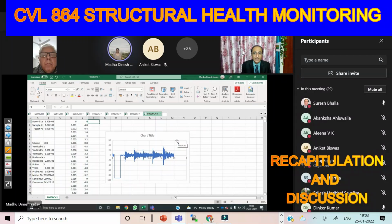So how do we define the 9th peak? This first file has peaks from 1 to 5, so the next file will have the 9th peak. That's how you randomly choose the peak and find out what the voltage is at that particular peak. Then you convert that voltage into strain. That's how you get the dynamic strain measured by the piezo. Similarly, for the accelerometer also, according to your own entry number, you use the particular peak and you will be able to get it.